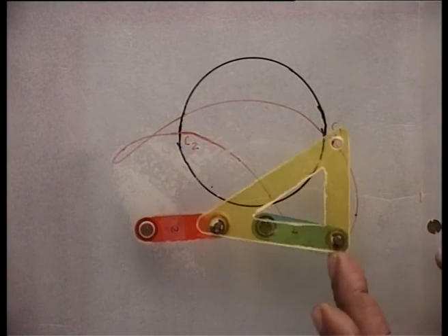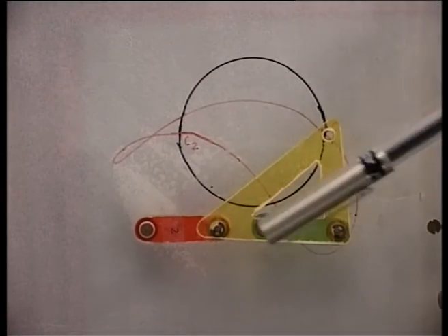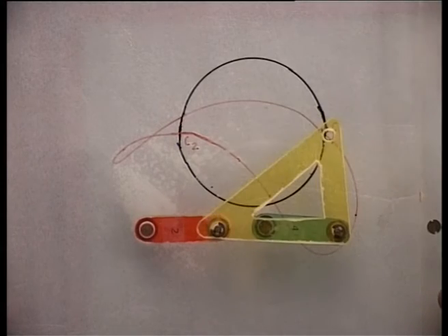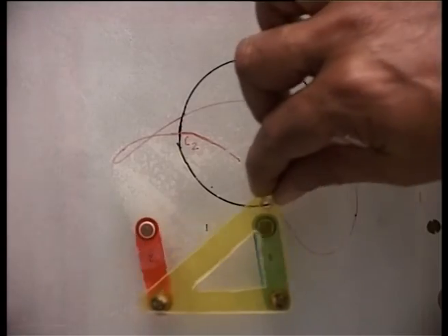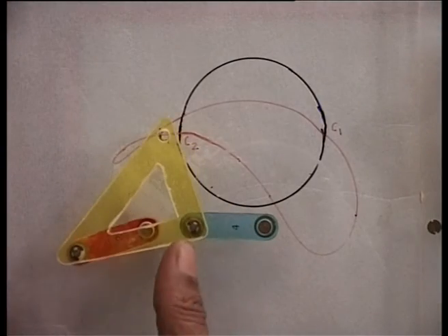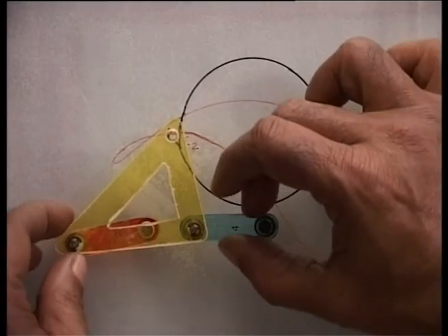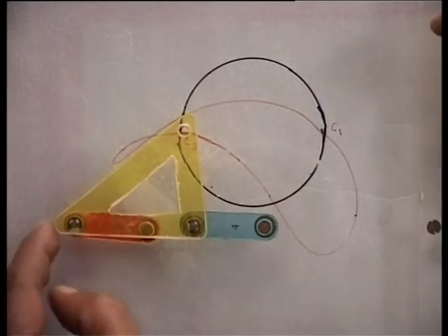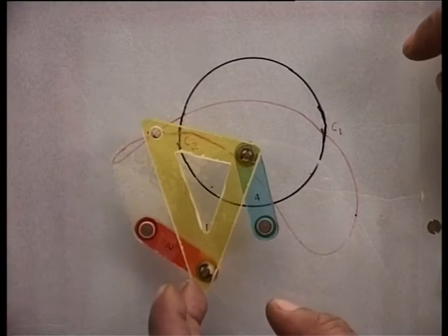This uncertainty configuration is true for all types of transition linkages whenever L min plus L max is L prime plus L double prime. Again, this is another uncertainty configuration. So, we can either maintain the parallelogram or it can flip back to anti-parallelogram configuration.